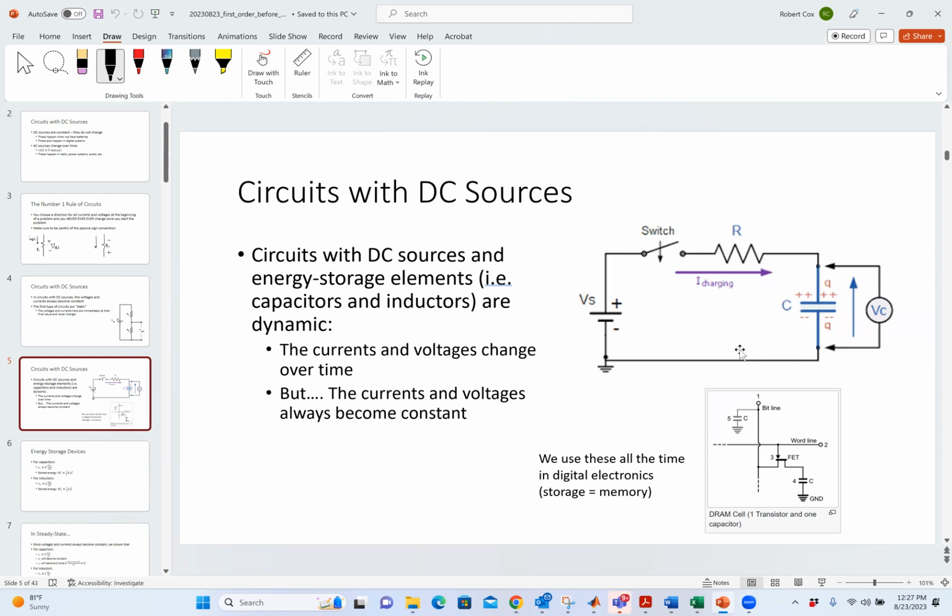All right. And so in this case, when that capacitor charges up, what does it look like? We can replace the capacitor once it's charged up with what kind of circuit element? Open circuit. All right. Once the capacitor is charged up, it's an open. Once an inductor is magnetized, that's the right term, not charged, but magnetized, then we say that the inductor is a short circuit. Okay. Until then, it's a capacitor or an inductor, and we have to analyze the circuit.